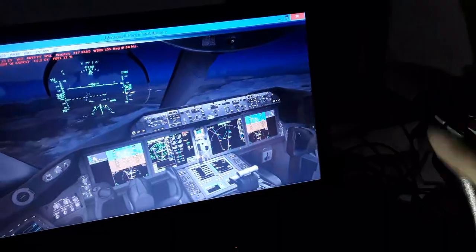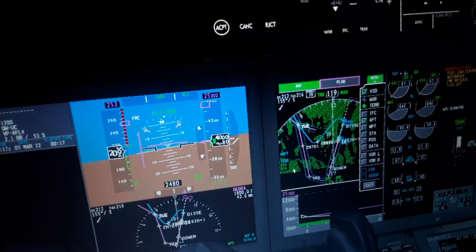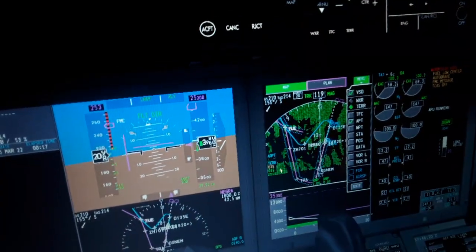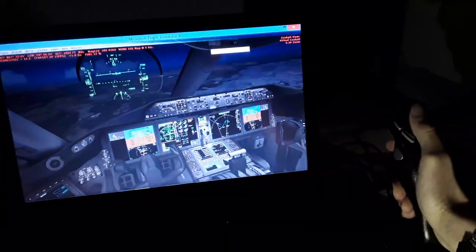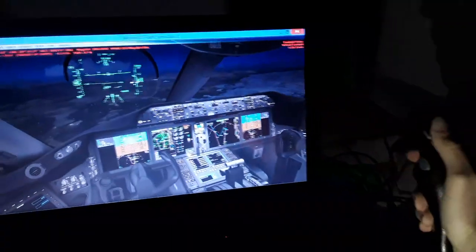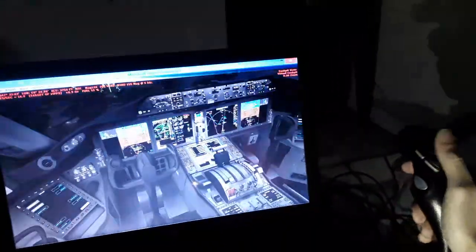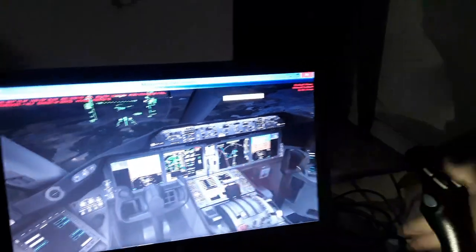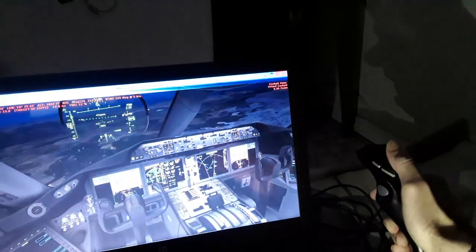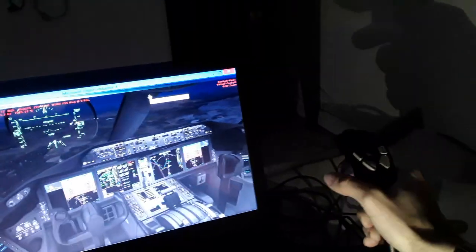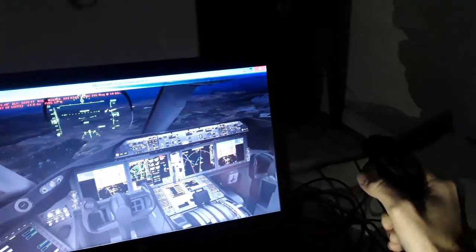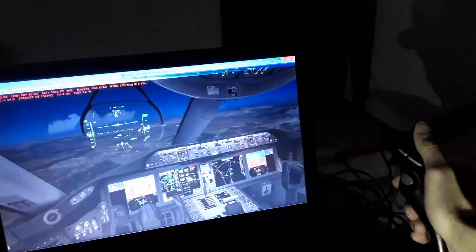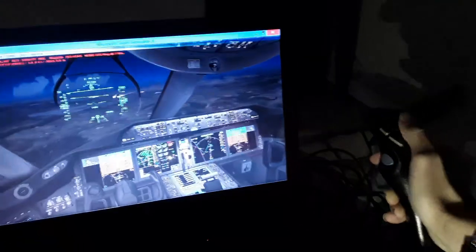So we have 3 more minutes left. You can see we have also the LSZH localizer, all the information. We need the airspeed, the needle. We need to make a little bit of a turn to the right, rather pedals to the right for alignment. And we need about a couple more minutes for approach and landing. Also flaps maybe full as we are approaching. We have some side wind. We need to use all flight controls to combat the side wind and the gusts to make maneuvers for approach and landing.